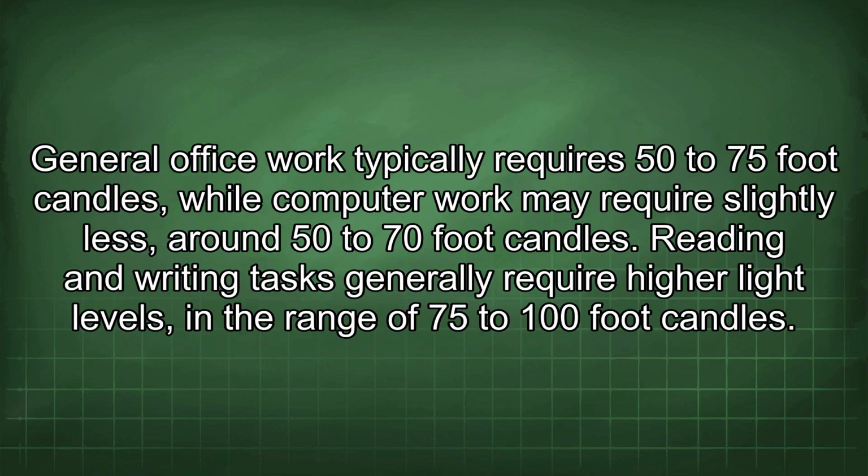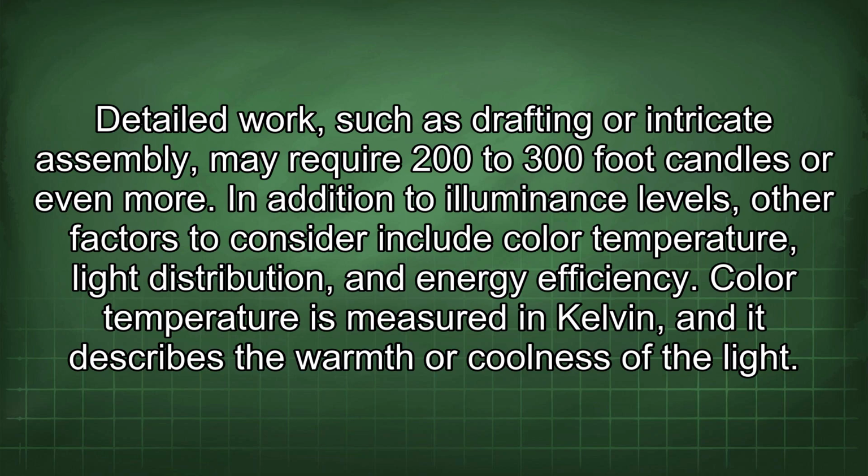General office work typically requires 50 to 75 foot candles, while computer work may require slightly less, around 50 to 70 foot candles. Reading and writing tasks generally require higher light levels, in the range of 75 to 100 foot candles. Detailed work, such as drafting or intricate assembly, may require 200 to 300 foot candles or even more. In addition to illuminance levels, other factors to consider include color temperature, light distribution, and energy efficiency.